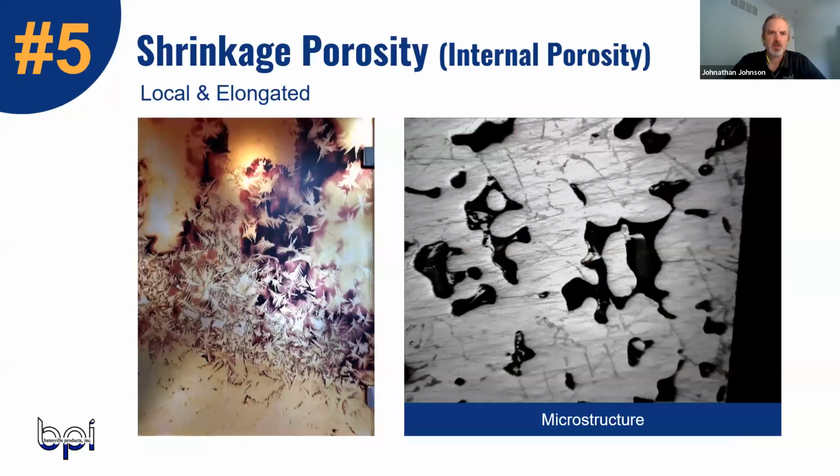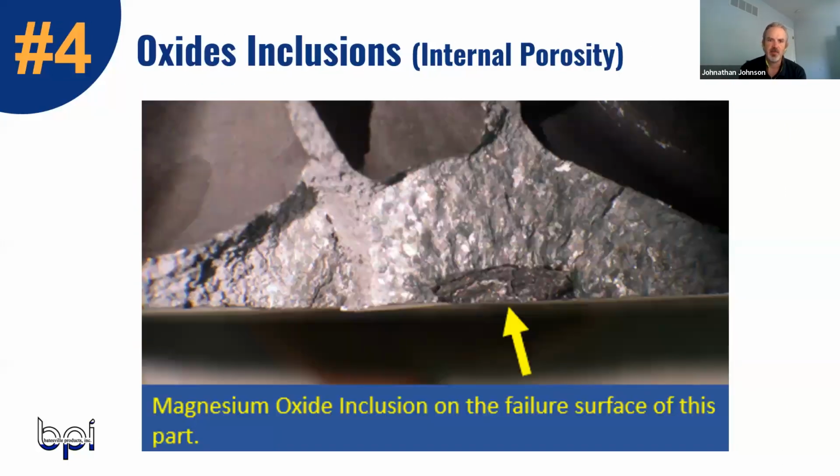Hey, Monty, we have a question. David wants to know, it seems like the speed of the pour, fast or slow, is important. How is the pour time controlled? Pour time is set up with a timer on the press itself, as far as how many seconds it takes to tip. So that'd be on the permanent mold side. Yeah. As far as gating goes on a sand casting or anything like that, normally to control it, you choke it or open it up depending on how fast you want to go.